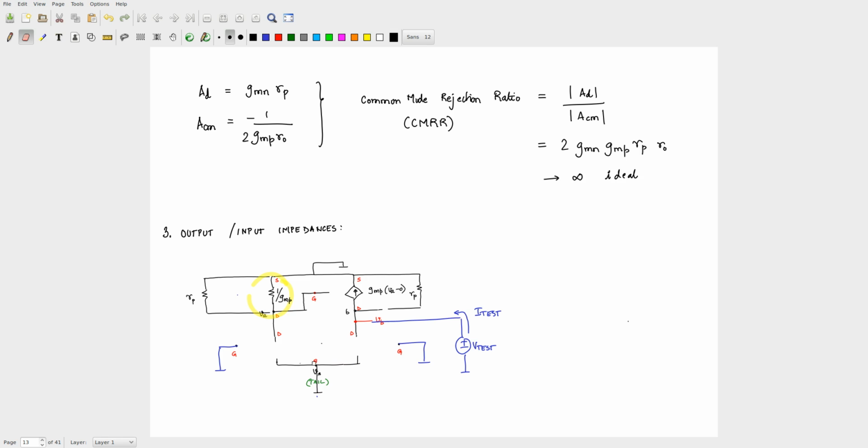Okay, so all of this effectively disappears. Then what happens? What is the current that is flowing in here? That current is 0, which means that Vg here or Va is essentially going to be 0, right? Why is it going to be 0? Because there's no current flowing in here. This is at 0 potential, so Va is at 0, right?